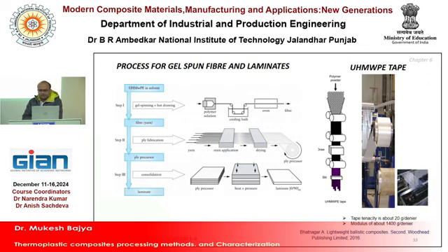Then from this precursor you can also change the orientation. In the last 2-3 classes, ply, different cross ply or 0/90 or different types of lamina and laminates were discussed. So this is the lamina, and then you prepare the laminates as per the direction, like 0/90, 0/45 as per the requirement and where you are getting the better result. Generally it is reported that 0/45 configurations give better performance.